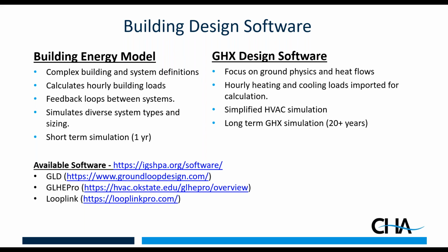So it is looking for hourly or monthly heating loads that you are going to input from a different program. And so it has a very simplified HVAC simulation that will capture some of the changes in performance for part load, but it's a very, very simplified simulation compared to what you're doing in your building energy model. But because we've limited that, we can simulate that much more easily over a long time, like 10, 20, 30, 40 years.